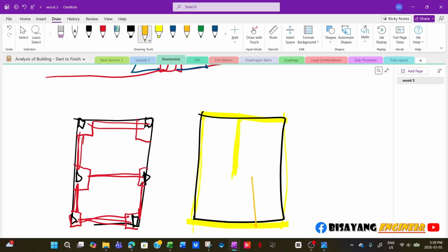So that means if there's a beam, then there's a telepost, then there will be a spread footing right there to support. Now, this footing usually, because we are in a cold region, has to be embedded below the frost line. And typically, what we do is say this is your footing, and then this is your stem.